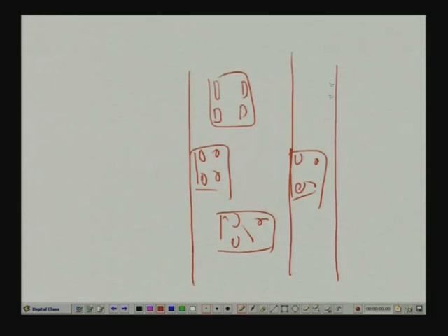They are not going to follow any particular path, they are going to be distributed across the carriageway width. One vehicle may travel along this path, another vehicle along this path, another may take a slightly different path. So, the wheel load positions are going to be distributed across this width.